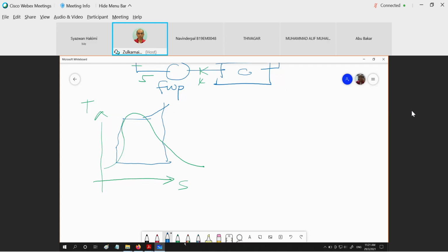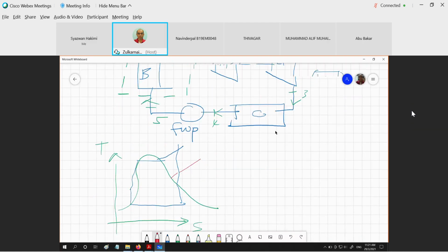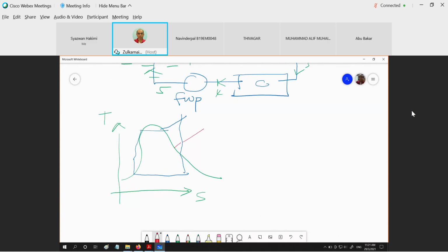Right? And we did 2 expansion process. So meaning that we are going to have an intermediate pressure right here. So when we refer to this schematic diagram, that is 1, 2. Okay, this is state 1, this is state 2. And then this is state 3, this is state 4, and this is state 5. If we look this application of our multi-stage expansion, it does not give us any increment of W net. Because whether we are using only 1 turbine or using 2 turbine, the turbine output is still from 1 to 2, 2 to 3.